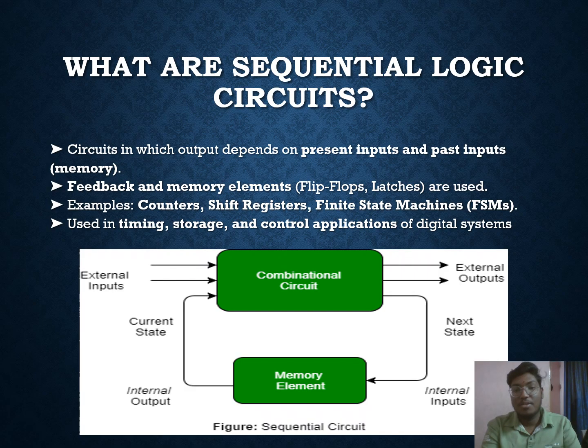Okay, now we discuss sequential logic circuits. Previously, we discussed combinational logic circuits, which do not have a memory element or feedback element. By adding a memory or feedback element to these combinational circuits, we obtain sequential logic circuits. So the output of a sequential logic circuit depends on the present input and the past output.